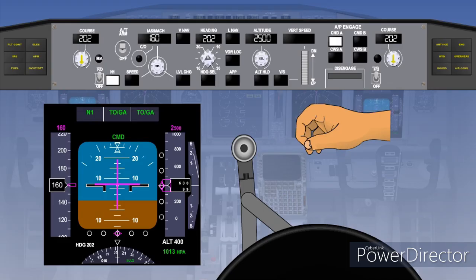As the aircraft climbs, the pilot will move the flap from a landing to a takeoff position and select the gear up. The autopilot will not operate the gear or flap. When the aircraft has passed 400 feet above ground level, any roll or pitch function of the autopilot can be engaged. Typically, heading select and vertical speed, or lateral navigation and vertical navigation, if a missed approach procedure is part of the active route. The pilot can then use the autopilot to reposition for another approach at the same airfield, or fly to an alternate airfield, whichever is appropriate.